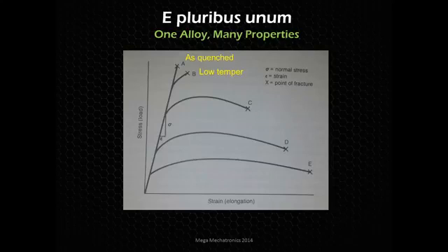You need to temper it, any temper. So let's say we do a low temper where it's at a lower temperature or shorter time or a combination of both. Here's maybe a higher temper where you are bringing it up to a higher temperature and you're leaving it there for longer. And here's possibly a normalized material, and then a full anneal where you're resetting it. And you can see the wide range. So anything in between A to E, you can give that property to that material, and that all depends on your application.